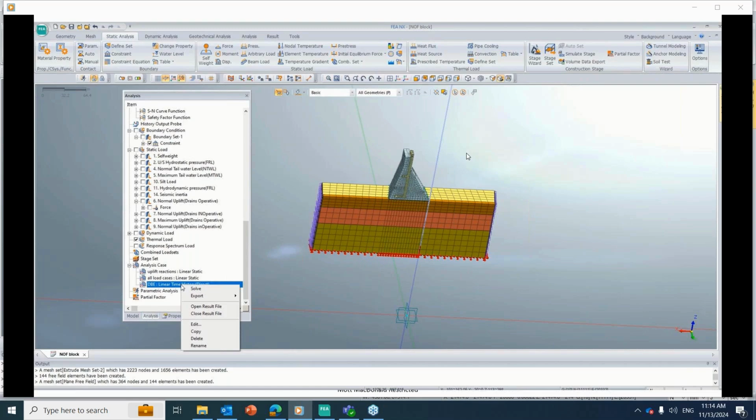Even then, some structures were fine, but for some unimportant structures, it was found that this is again uneconomical. Those structures are not of that importance, their failure is not catastrophic. So maybe we can include one more factor, that is the importance factor. So they included one more factor called the importance factor: peak ground acceleration divided by 2, into Sa, the response of the structure, into the importance factor.